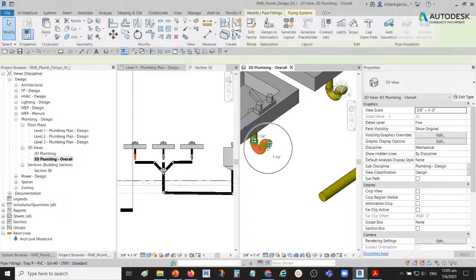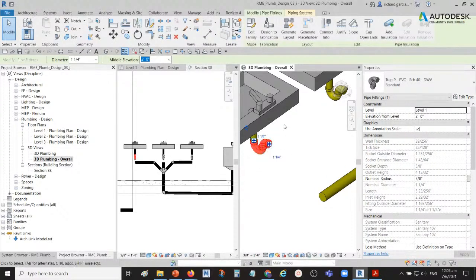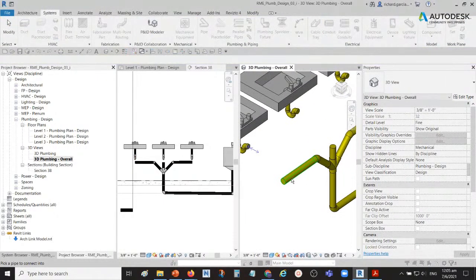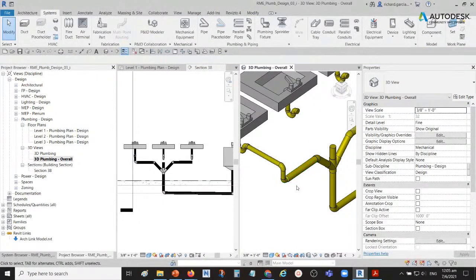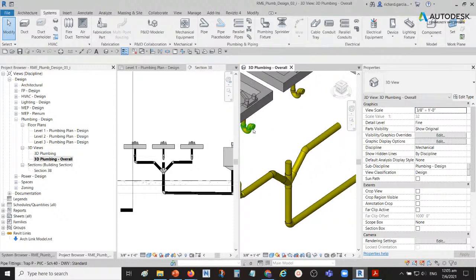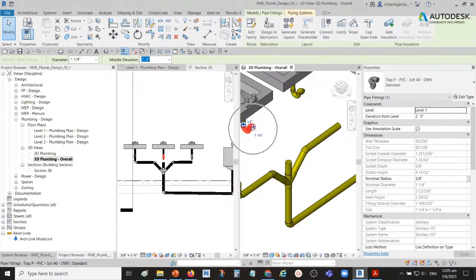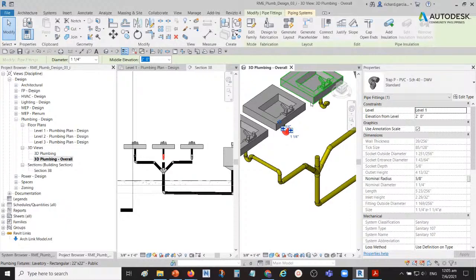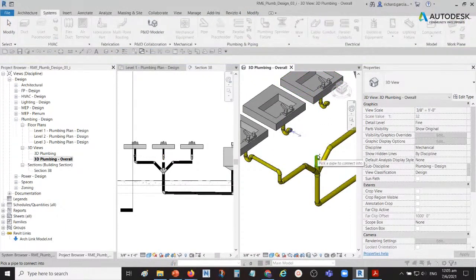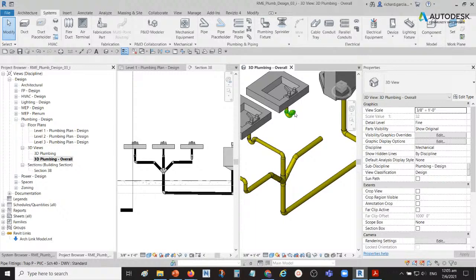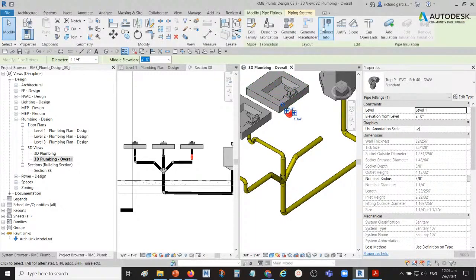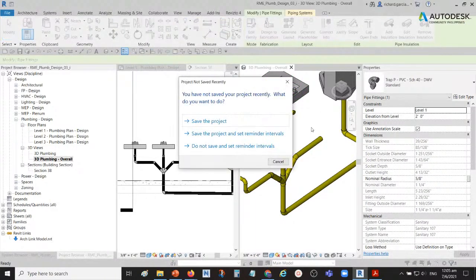So you can click that fittings, and then there is this connect into tool. Just click that one, and then you click the pipe. Okay, so that is another way of connecting your pipe. Connect into, you click that, there you go. You click that, connect into, and then oops.